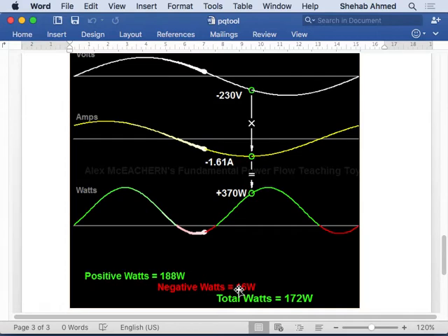There's a lot of work you can do on the power electronics side to improve this, and you can add capacitors to the system where you have a lot of inductors in the system. You can compensate the negative reactive power with some positive reactive power, right? So you can do things like that. And Kahramaa as a utility requires big industrial facilities to do things like that to improve the power factor. Ideally, we would like the power factor to be unity, so the angle between the voltage and current to be 0, but it cannot happen yet.